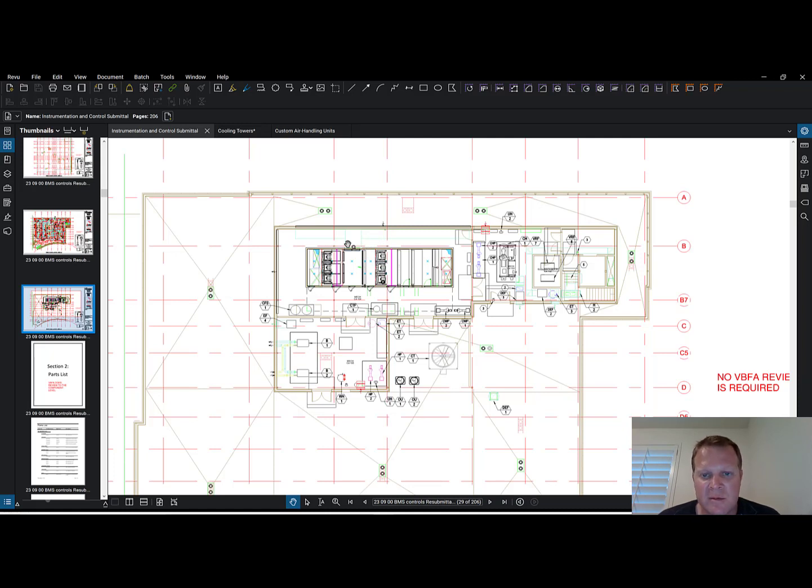At least put together a decent plan and understand what the mechanical contractor that we're going to hire, what their plan is. Maybe this is all crane, and maybe it is all fabrication offsite and it's going to come in sections. And so definitely you're going to have to leave a roof off for a long time. If you're going to leave the roof off for a long time, how are you going to get to the finishes down below? Oh, yeah, that's a problem, right? Okay, we might have to sequence this. We've got to get this watertight because this is up on the roof. We can't do any finishes. We can't drywall, do any insulation or anything until we have this watertight.